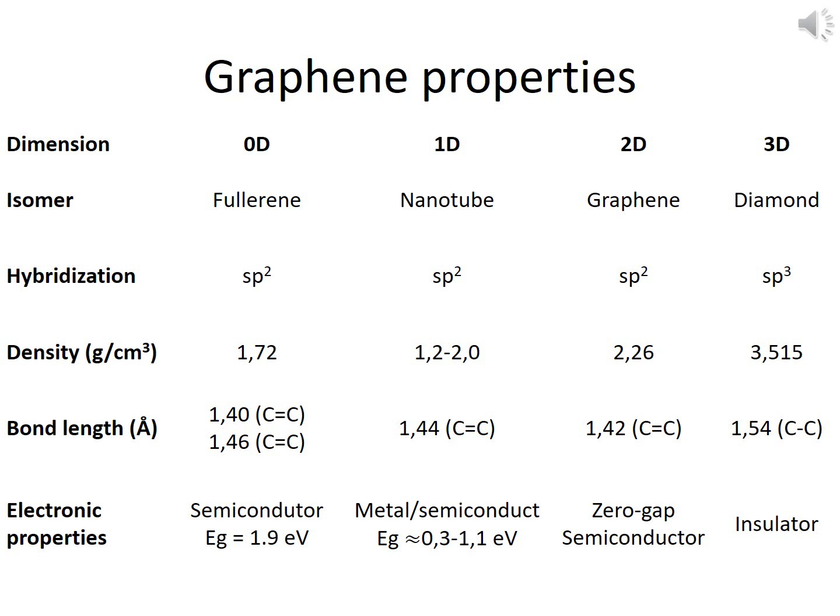The transport and optical properties of semiconductors and insulators are determined largely by the electronic band gap. The band gap is the energy required to promote a valence electron bound to an atom to become a conduction electron, which is free to move within the crystal lattice and serve as a charge carrier to conduct electric current. If the valence band is completely full and the conduction band is completely empty, then electrons cannot move in the solid.